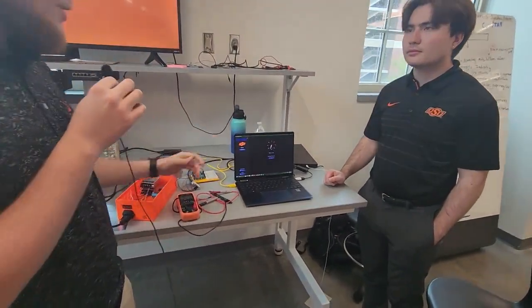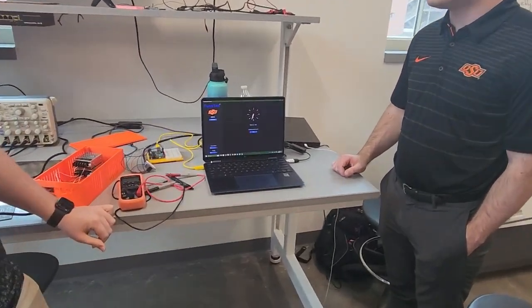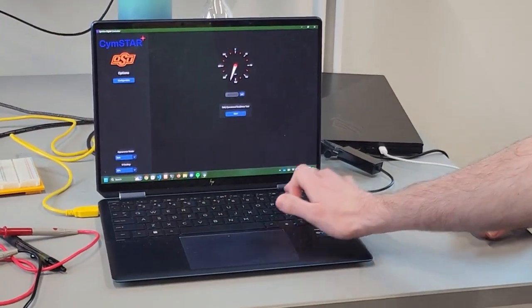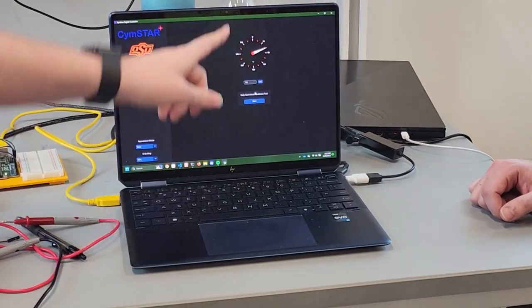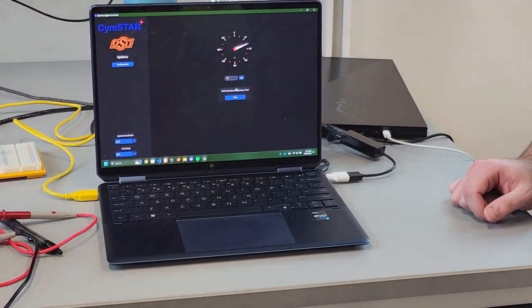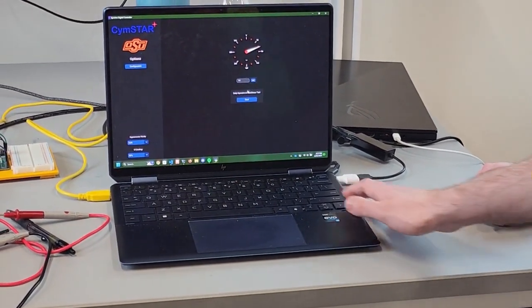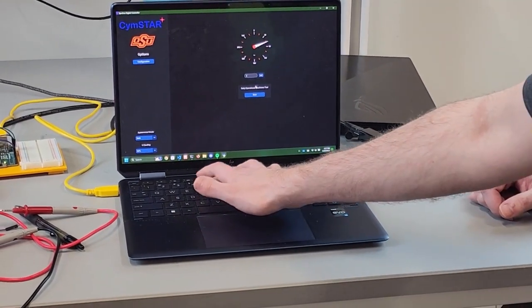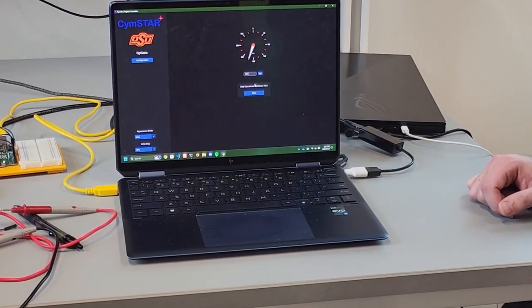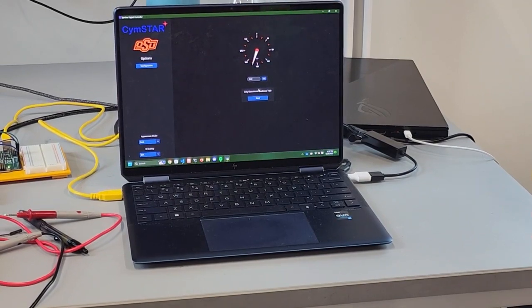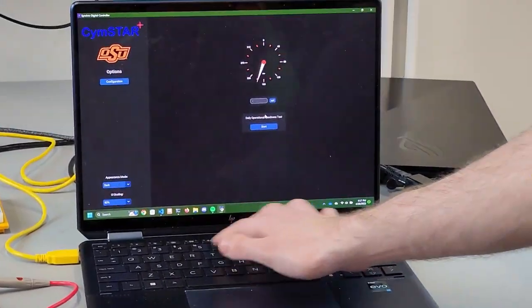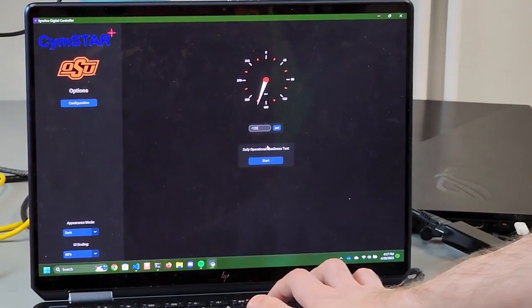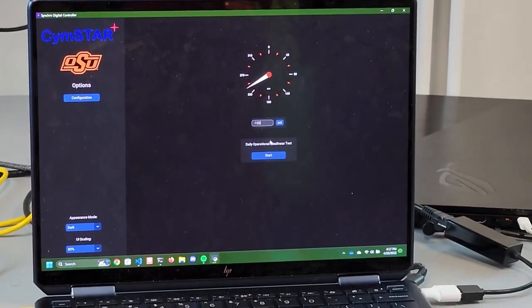You can enter the angle that you want on the transmitter side, and it will rotate to show what the current angle should be, and then as you change it, it will actually change it on the receiver side, and it communicates with our device over the Ethernet protocol. So as we adjust it, it will change the digital potentiometers to change the voltage to get the correct signals.